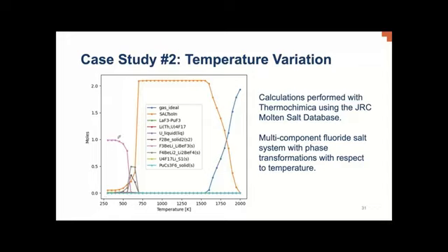Obviously not quite realistic, but as it's heated up, you can see that initially you basically only have some solid phases formed, and some molten salt starts to form at low temperatures, but at nominally 600 or so Kelvin, everything melts, and you have a predominant melt region right up here, up to a point where vaporization takes place.